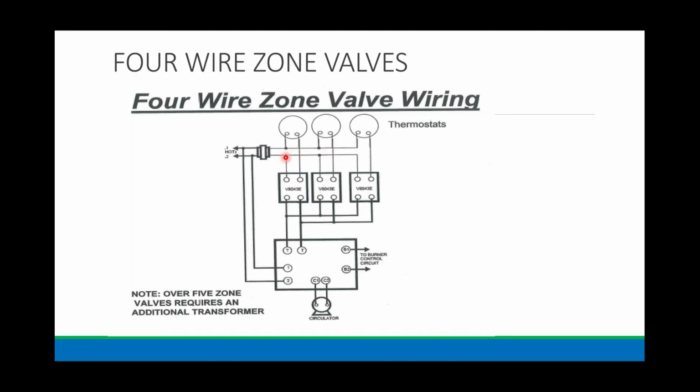And then down here, and these would be your yellow wires here, gents. And then down here, your 2 reds, the end switch, well, one side of each end switch is ganged up together to this wire nut. The other side of each end switch is ganged up together to this wire nut. And then we take one wire and one wire down to T and T on the boiler aquastat relay.